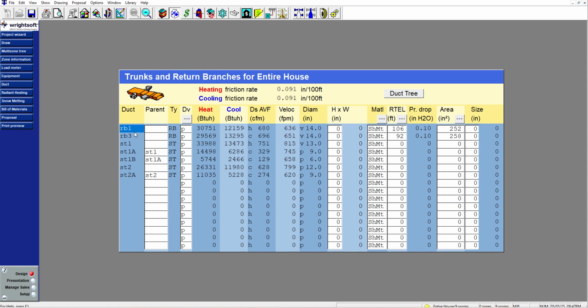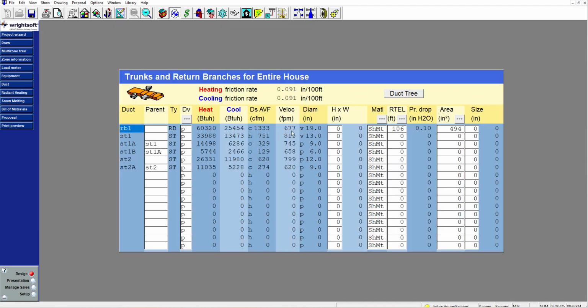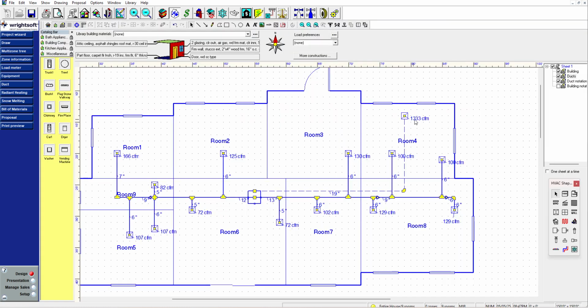But again, let's real quick. So here we have two, 630, 650, and they're each 14-inch ducts. If I were to delete one of them, head over back to that tab. So now we have not violated the 700 foot per minute requirement, but that's because the software automatically had to bump up the diameter significantly from 14 to 19. Okay, but this means now that the trunk and the register size has to be quite large. Because look at that. Look how much cubic feet per minute of air is coming through it. Okay, so let's bring that back. Let's bring back that second one. All right.